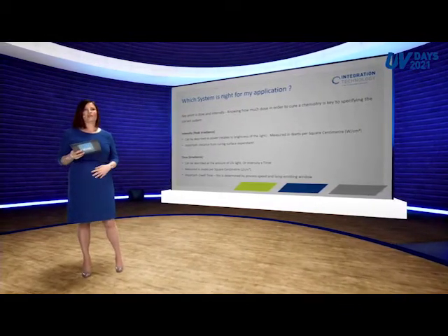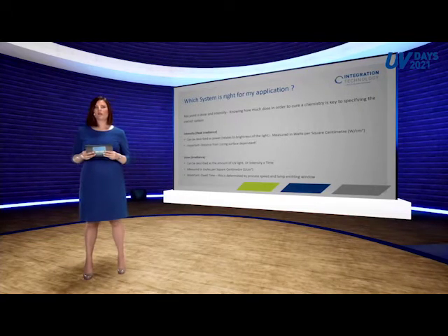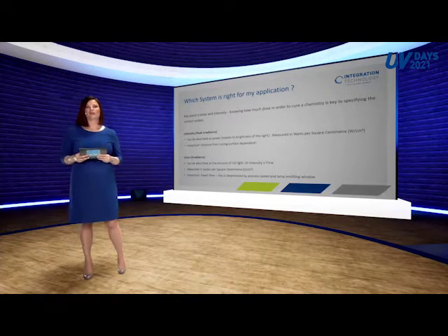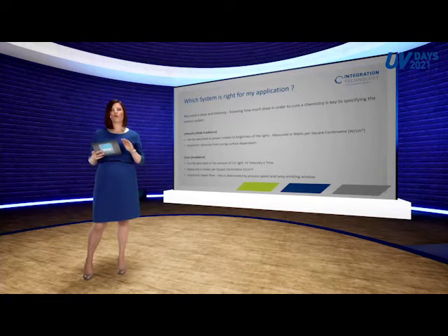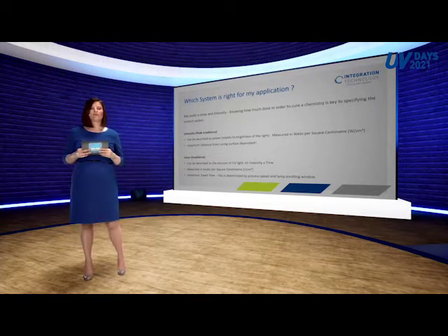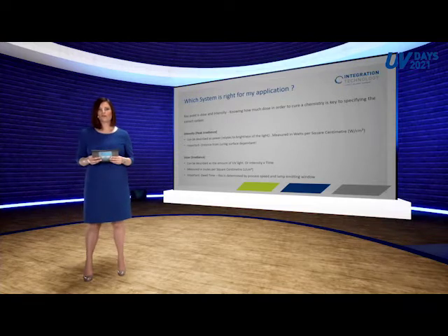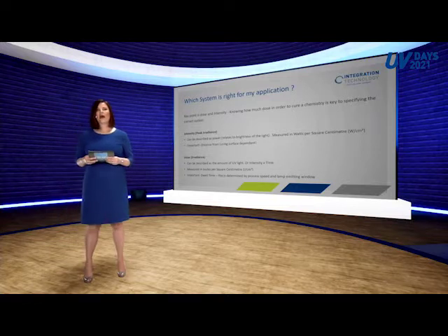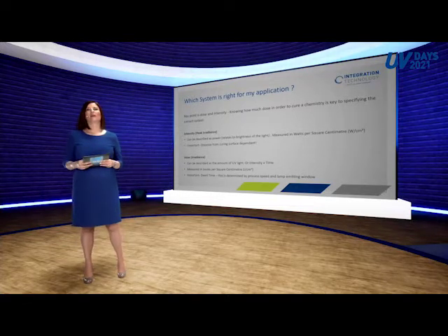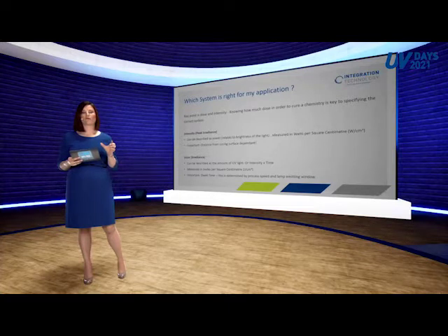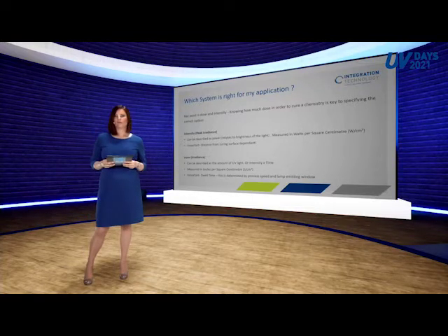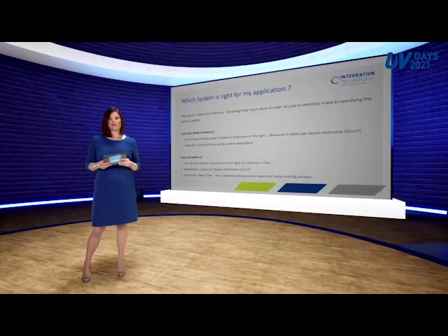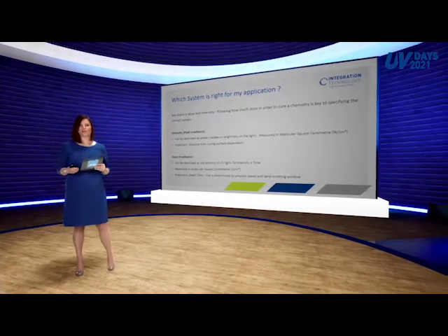And also then, so we have dose. Dose can be also then described as the amount of UV that is at that point on the substrate. And there it is dependent also on the speed normally of the system, of course, that makes sense, intensity versus speed. And also the emissions window of the lamp. This also has an effect, obviously, because of the size of this. So there's the basics about them. So how does this apply to the application?